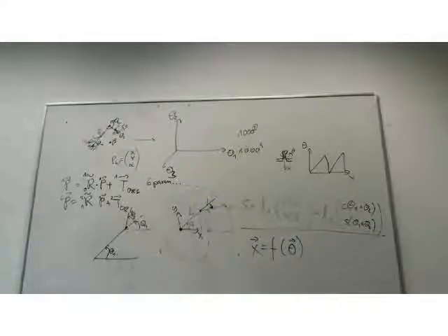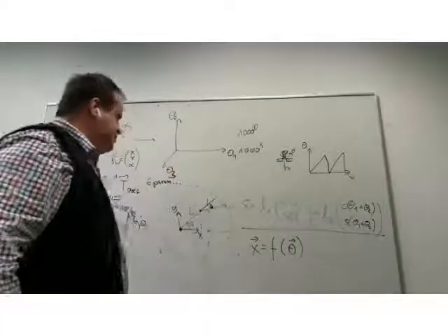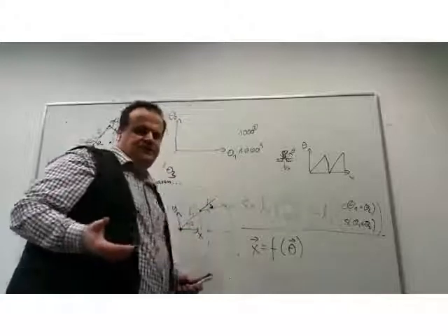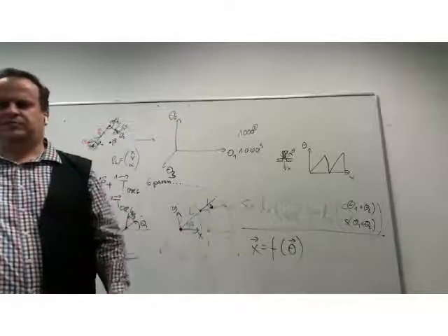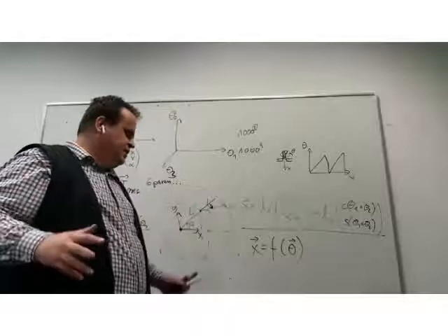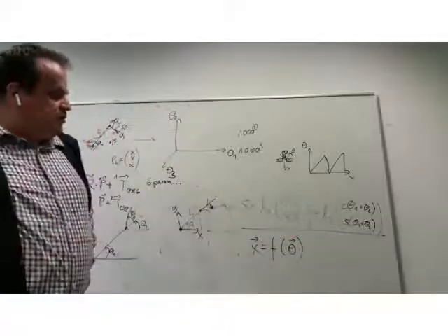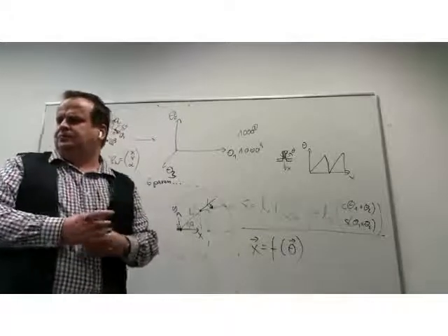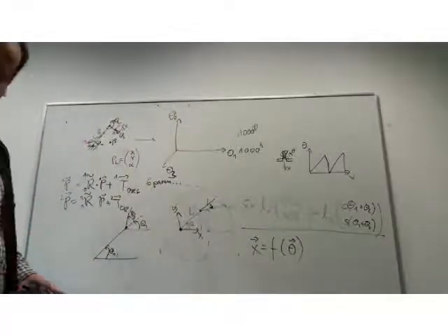What we're having as a problem is, of course, our robot is usually three-dimensional, and to have a robot which can cope with a general motion state, we need to have 6 parameters. So I will have here 6 joint parameters with a lot of structural geometry, which is moved around by motion of the joints. That's why we need to see how our transformation is defined.